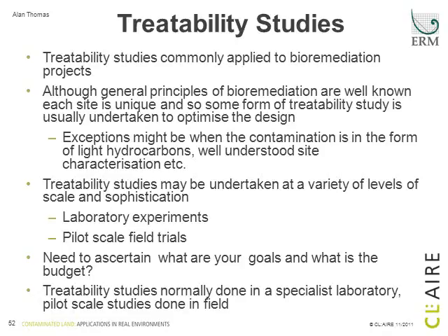Now, treatability studies may be undertaken at a variety of levels of scale and sophistication. Typically we may look at laboratory studies or undertake pilot scale field trials. What you undertake really depends on your goals, the budget, and what you're trying to understand. Treatability studies are normally done in a specialist laboratory. Pilot scale studies are done in the field in a portion of the site that you want to treat, where you can really focus on some of these site specific characteristics.